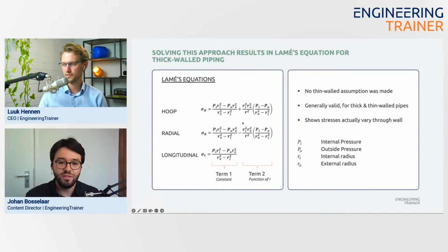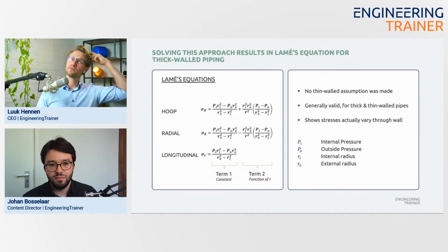Right, fair point. So in that sense, the radial stress, I believe, doesn't have to be compressive. If the constant term is high enough, because the constant term is positive, the second term doesn't have to make it compressive. So what situation would provide that, if we have almost a vacuum or something in the pipe?